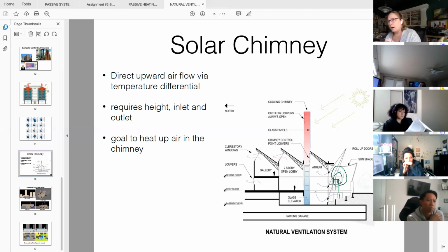The only reason we were allowed to install that, though, is that in California, for any conditioned space, they look at the energy performance because they assume you're going to be air conditioning it. They'd look at the performance of that glass and say you don't meet the energy standards. So the only reason we were allowed to do this is the public areas of the museum are not conditioned spaces, and so they didn't have to follow Title 24 regulations of energy performance.